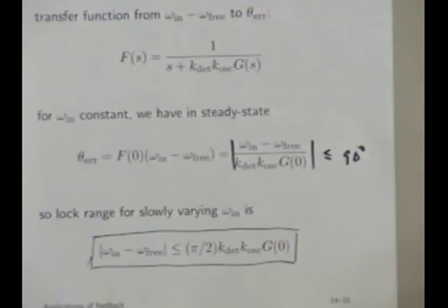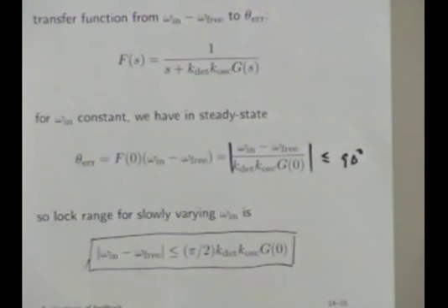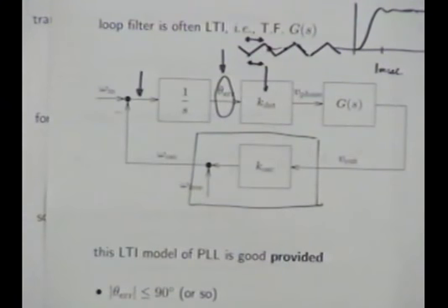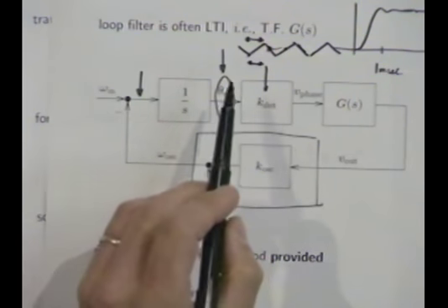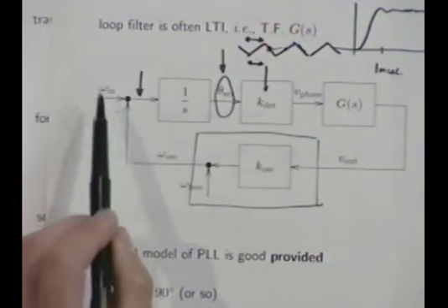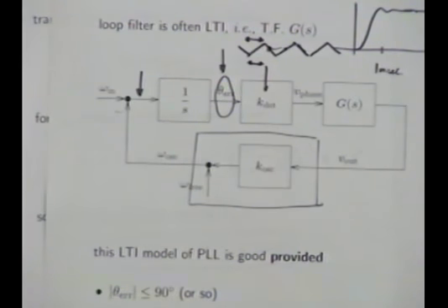Professor Boyd, how are you calculating the transfer functions? Are you doing it directly from the diagram? Yeah. You mean how do I do it personally? A lot of these things I can guess and write it down, and just look at it and figure it out. But often I'm wrong. So I do it the way you do it, which is I sit down in a quiet place and I write out all the equations and I eliminate a bunch of things and I express this, the Laplace transform of this, as a linear function of the Laplace transform of that minus the Laplace transform of that. So that's how I do it.